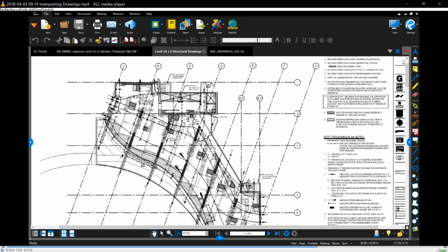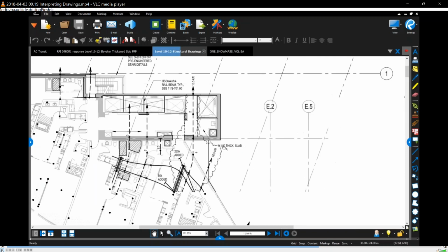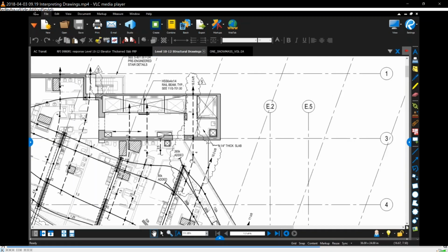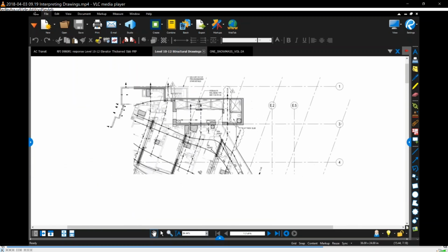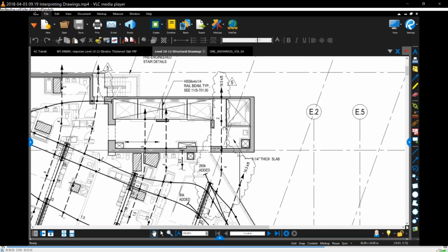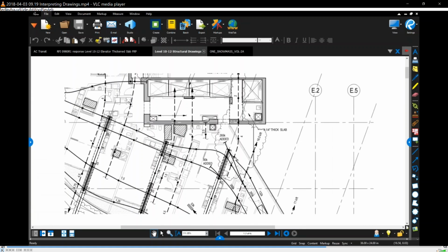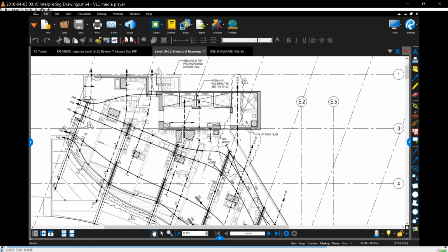And these are the structural drawings that it came from. 9 1/4 inch slab again. There were cables. So in this particular job, here's a more recent structural drawing that calls out for post tensioning. These dashed tendons are uniform cables, and these hard line cables are basically the banded cables.